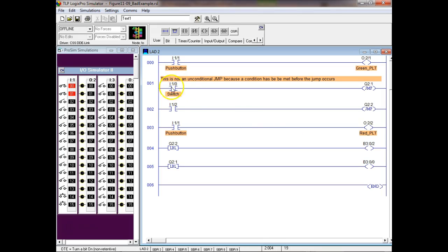So that means if I come over here, I could activate this jump. When this one's false, I could activate this jump, right? You understand? And if I do that, then neither jump would be activated. So this would be an example of a jump within a jump. I could have put the jump down here and jump backwards, and what you have to understand is that we can either jump forward or backwards. But whatever address you jump to, whatever label, it will eliminate whatever is in between the jump instruction and the label.